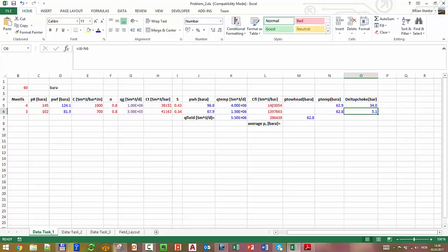What did you see just now? Let's click undo. Okay, that was the initial case, right? 12.8 and 2.8. What happens when my reservoir engineer comes again and says I want to produce exactly 1 million? You're going to say, oh, I just go and change the choke on template L, right? That's it. But you see, if I want to keep the same 500,000 rate from template M, I also have to change the choke in template M.